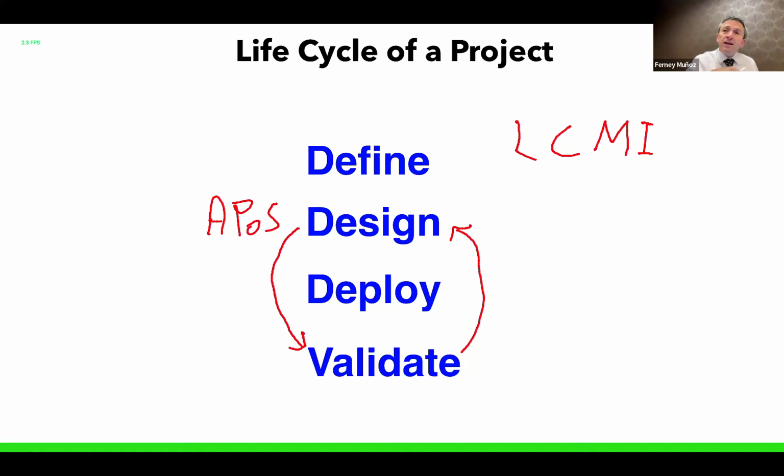So you feed that data, and then you measure walls, and you measure attenuation of obstacles, and then you go on site and look at heights and double check everything. So yeah, they told me the ceilings were 2.5 meters high, but hey, this is the reception area, this is really high, and if we're going to put it in the ceiling, it's going to be 5 meters.